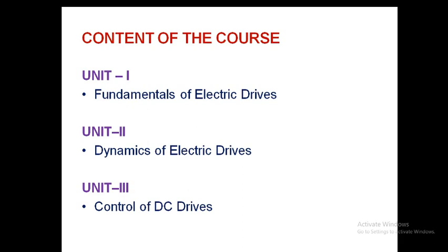If you reverse the motor speed with the power electronic converters, then that will enter into the second quadrant. By keeping the torque in the positive direction only, we are reversing the speed. Then it is in the second quadrant now.